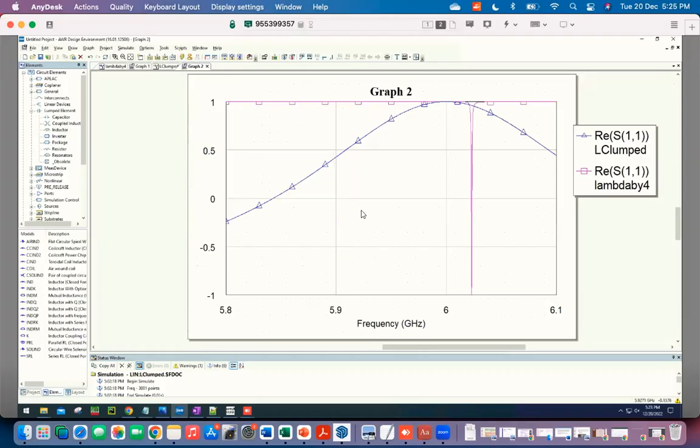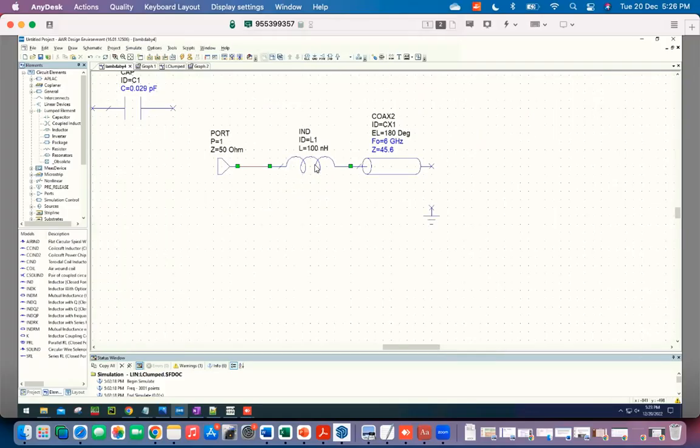But look what happened to the frequency. Shifted to the other side. That also makes sense if instead of an inductor, I had an inductor in parallel, 2 parallel inductors will reduce the inductance, so the frequency goes up. But here you need a much larger inductance. So one can actually do something clever here, which is not to put it in series, but to put it in parallel to ground.